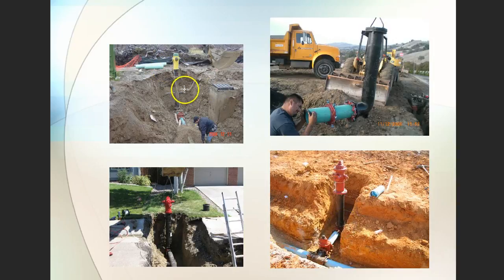In this picture up here, you've got the same thing going. You can also see they're putting tracer wire in. They put tracer wire in to put some metallic in along a plastic pipeline or concrete pipeline so the metal detectors can pick it up when they're trying to find the pipes. Tracer wire. And again, you can see how pipes change in the type of materials and the different transitions.